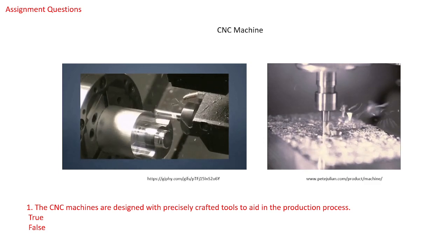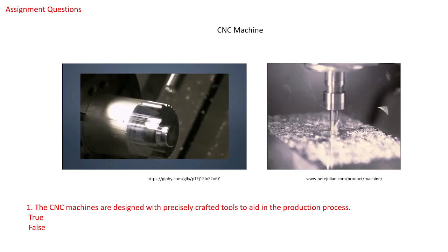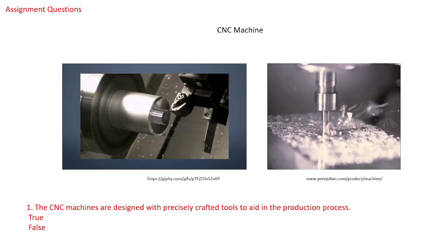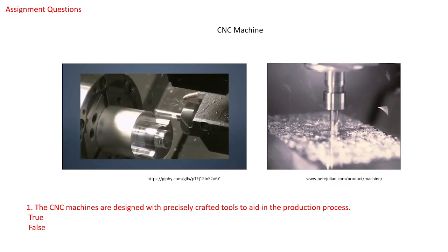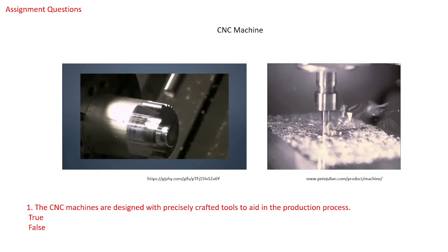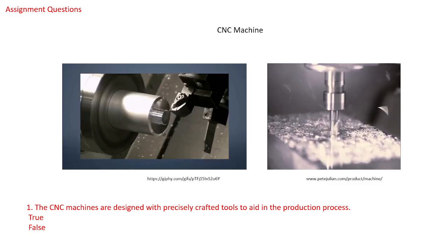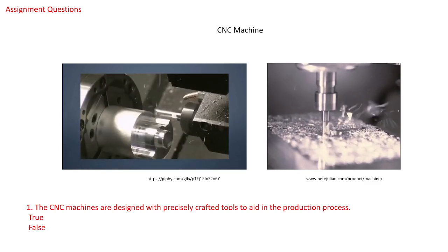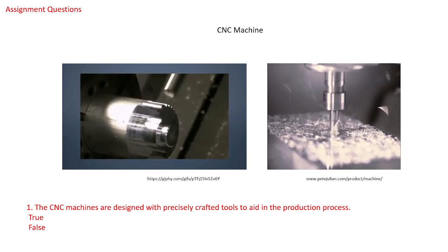Then come the horizontal machining centers. A CNC machining center or turning center which incorporates a horizontal spindle allows you to speed up your production process, ensuring that you are not interrupted. That orientation allows chips to fall away naturally, so you don't have to waste your time cleaning them off the table.